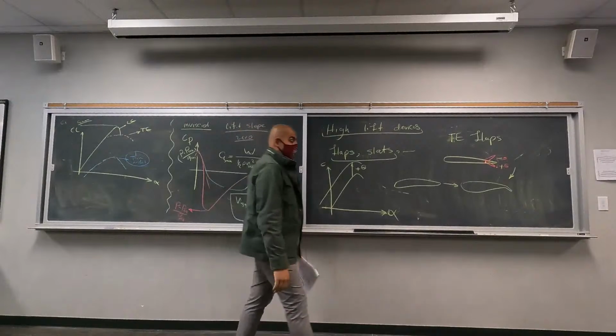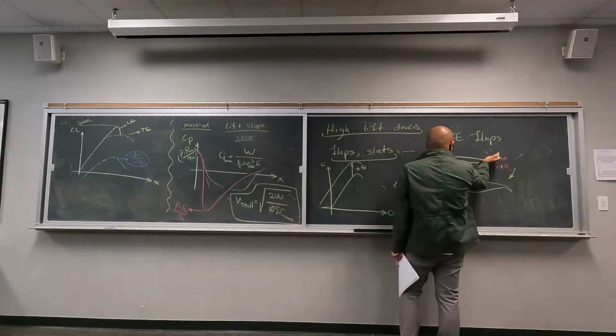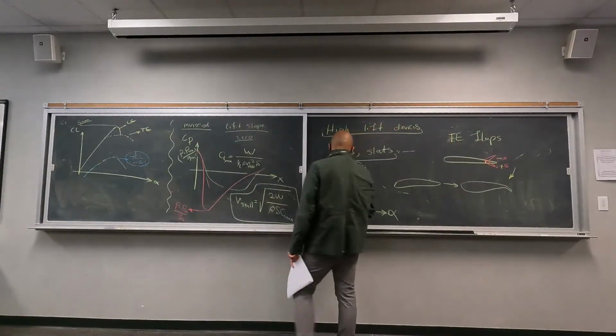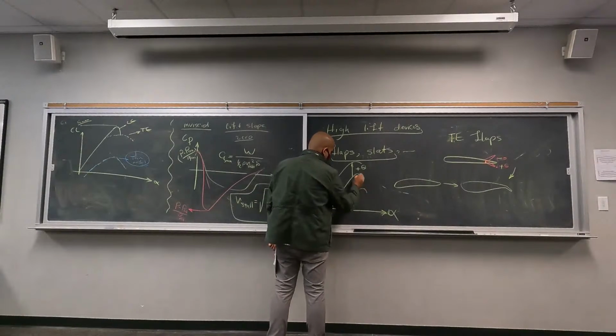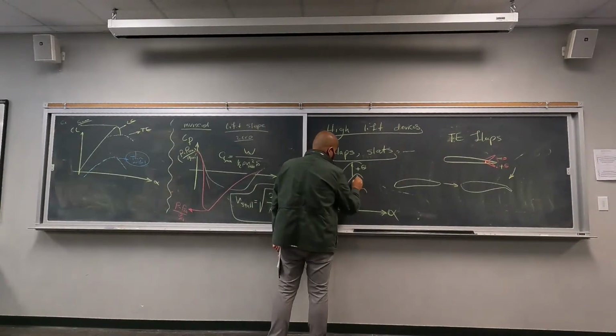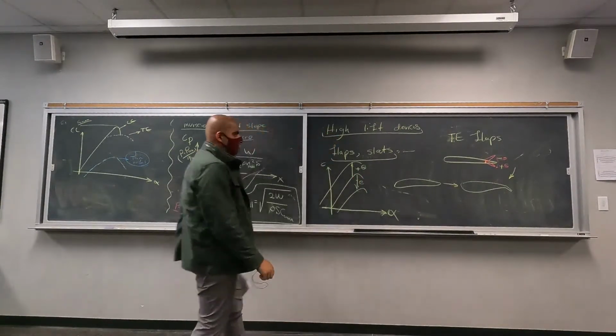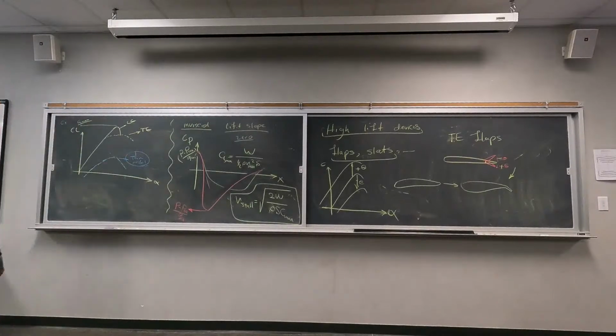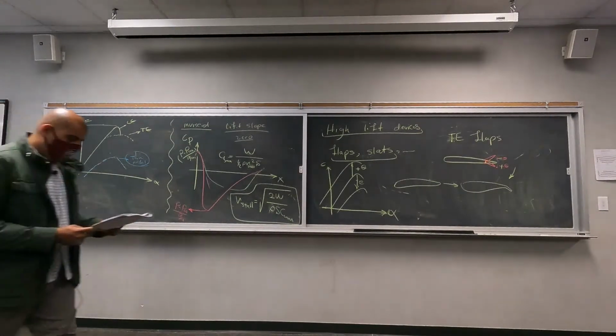And if you move this trailing edge flap in the other direction, your maximum is going to change. Okay? So you can see that even with a very simple mechanism, we can change how the airfoil behaves at different angles of attack.